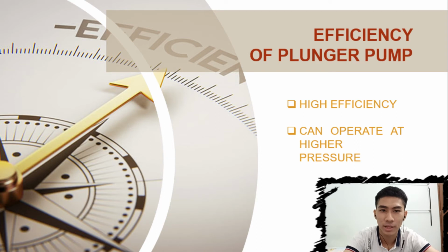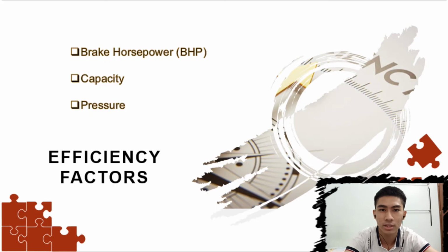For the efficiency of plunger pump, it is very high, which is more than 90%. It can operate at a higher pressure, which is more than 40,000 psi. There are several factors which determine how effectively the plunger pump works. First is the brake horsepower. It is directly proportional to pressure and capacity and inversely proportional to mechanical efficiency. Second is the capacity of plunger pump, which is directly proportional to its displacement per unit time. Next is the pressure, which is mainly the suction and discharge pressure in the plunger pump.